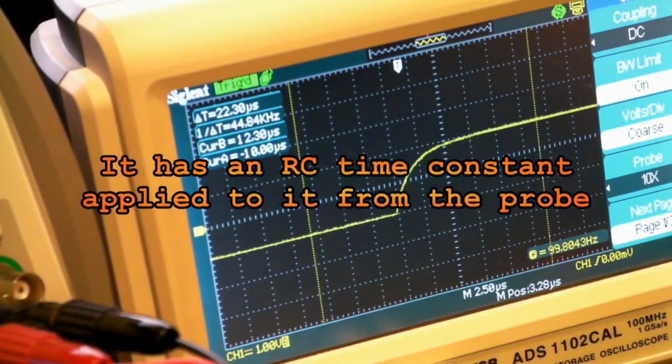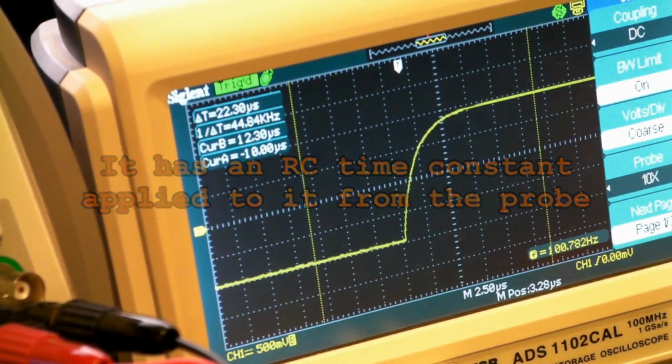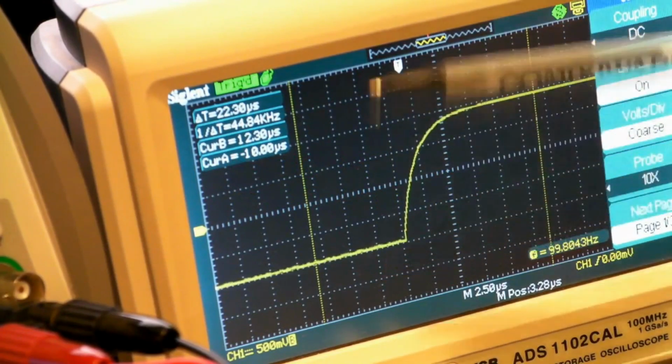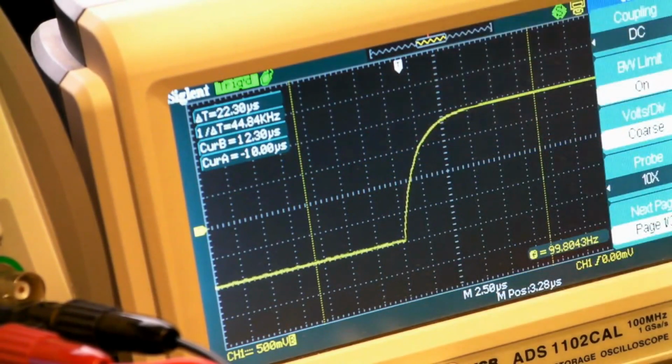So one of the things to remember for when you're doing this kind of measurement, 63%: if I increase the amplitude of this signal to 8 divisions and I simply measure across the first 5 divisions, that gives 62.5%, which is close enough accuracy, and it makes the measuring a lot simpler.